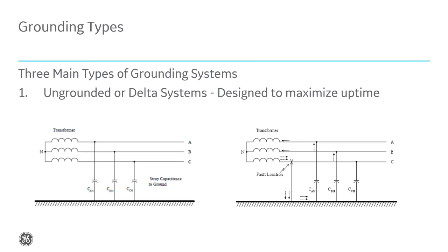A phase to ground and B phase to ground approach the square root of 3 times the nominal phase-to-ground value. In that case, we need to design our system so that the insulation level can handle phase-to-phase voltages, with some margin, obviously, so that if you do have a ground fault, you can still keep the system in service and not damage the insulation.